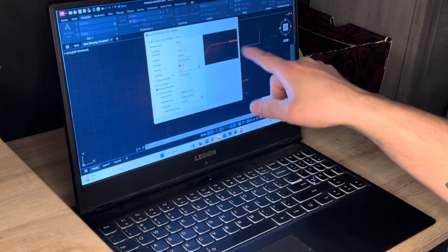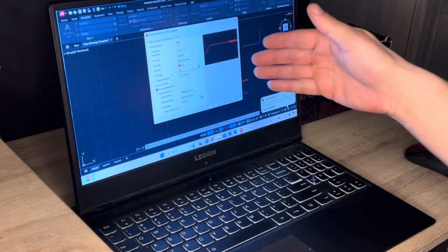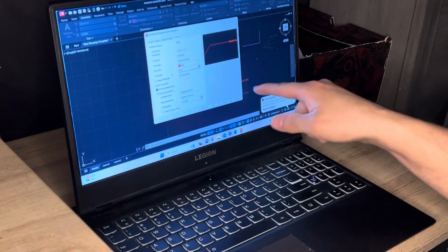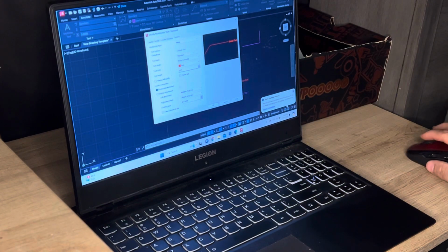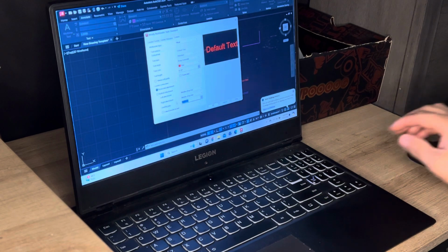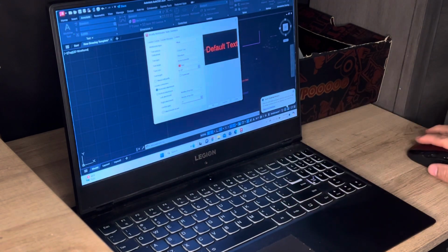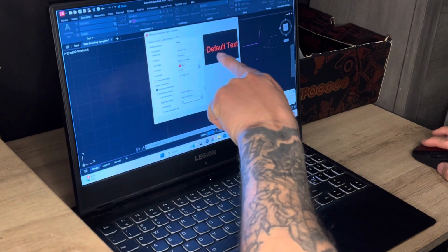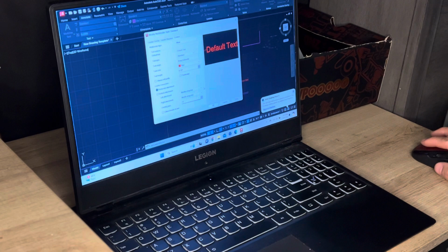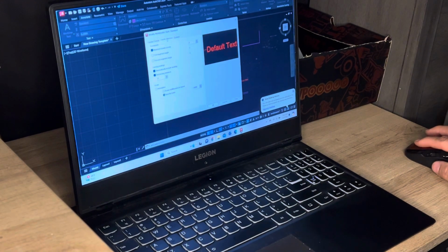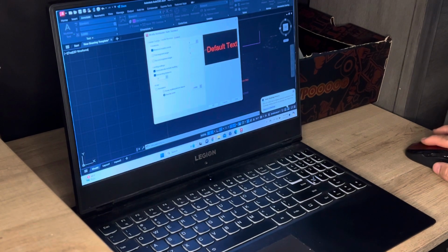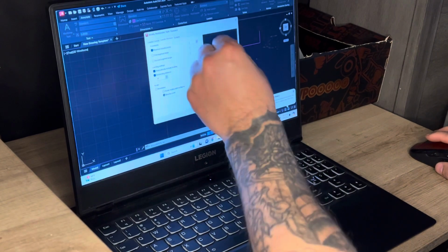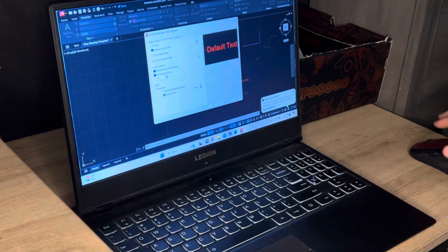And then the text height for my multi-leaders should read as the same height as my dimension lines. Alright? I did my landing gap 1 inch, which your landing is the little flat part that sticks out of the multi-leader. Alright? And the gap is the gap between the lettering and your leader. If it's too close together and you got a big leader, small letters, then they can kind of blend together.